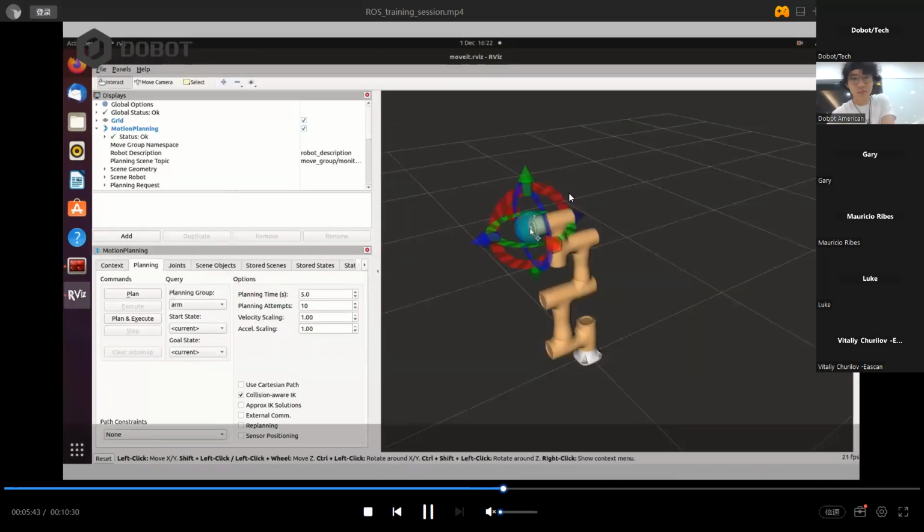All right. Basically, the GUI is pretty much the same, but you can see there's a little blue ball right here that you can drag. This is the center of your robot end effector flange. If I drag it somewhere inside the workspace, you can see an orange robot right here. This is the target position of the robot for this target point.